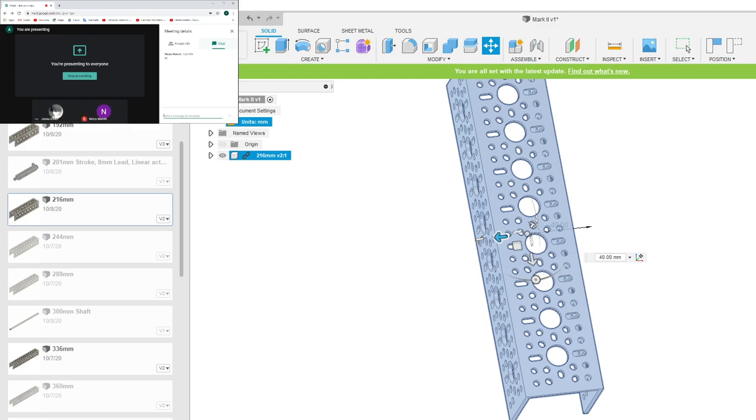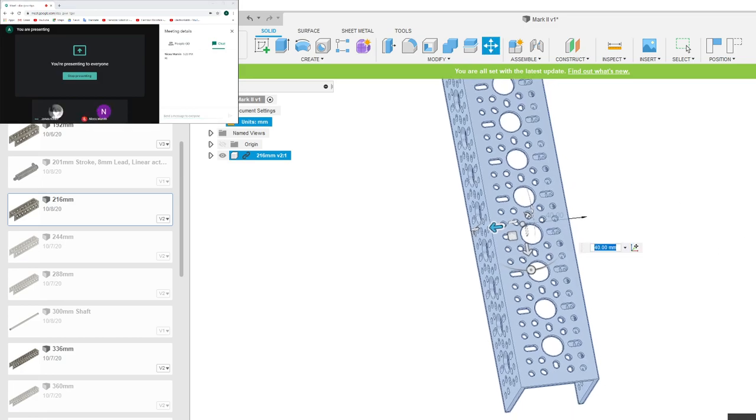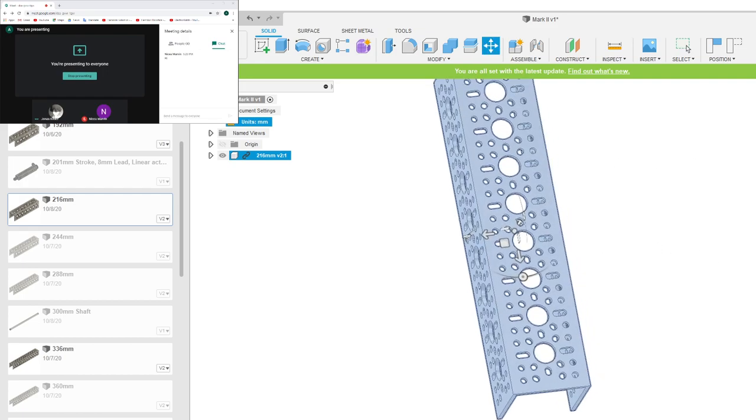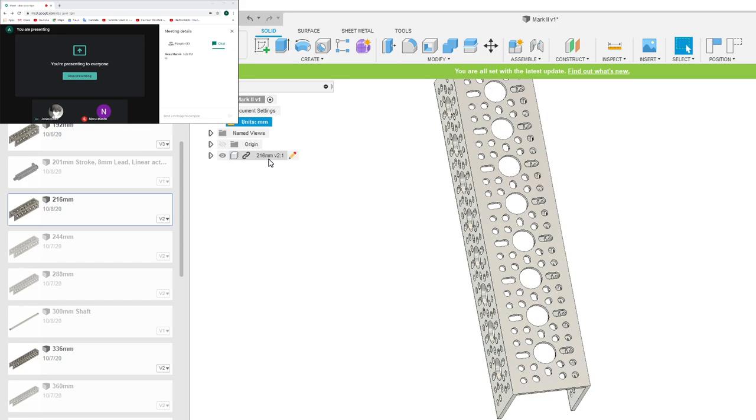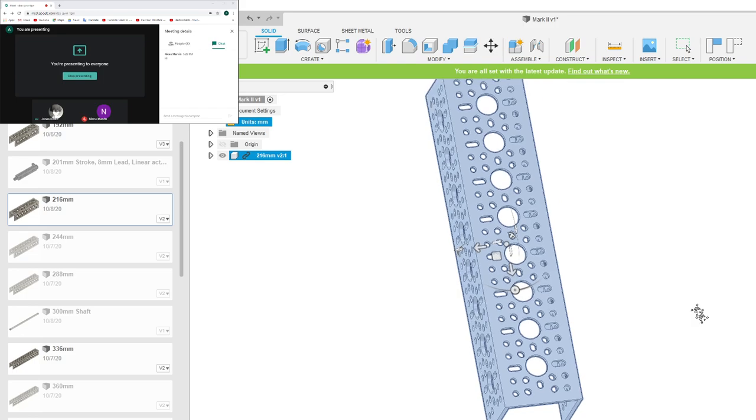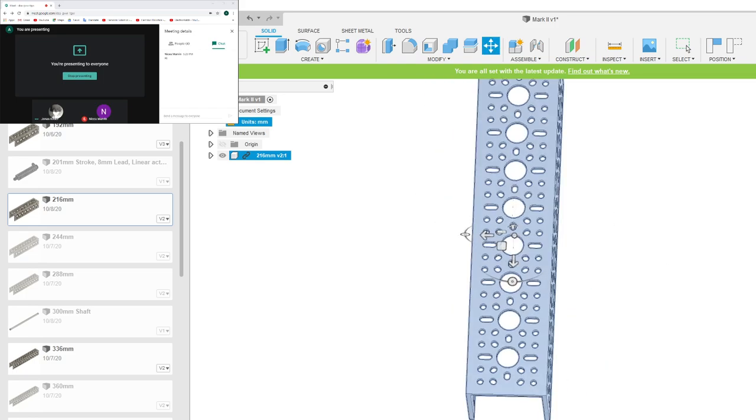So we just went over movement. Just as a quick recap, for movement, you double click on an object to select it and then hit M. Or if you come here in the browser, you can select a file or a part that you imported, and then you hit M, and you can move it from there as well.